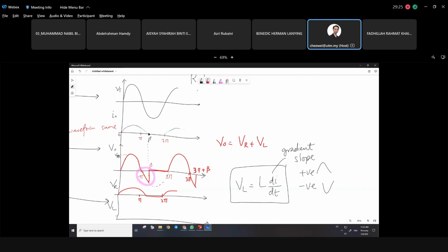Right, let's draw it. Before we draw it, we have to make the border. Okay, you see this is the peak value. From 0 to the peak value of the current, I have to extrapolate until pi. The peak value is the dotted line here. From 0 to the peak value, we have the positive slope. And from the peak value to beta, or the zero current, we have the negative slope. Okay, positive slope, you will have a sine wave like this. Can you see it?